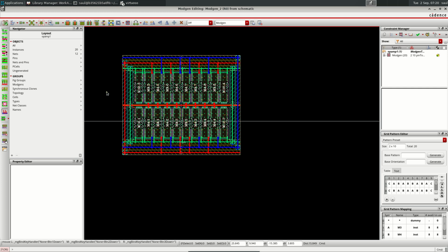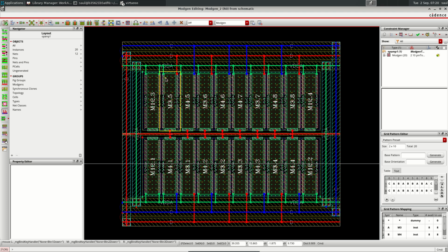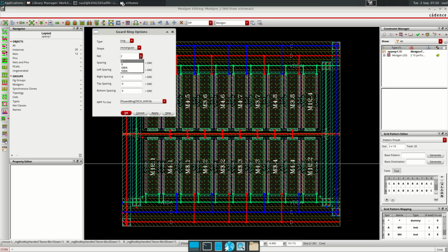Okay, as I mentioned before, I can continue connecting both sides if we want to greatly improve the connection and lower resistance, but maybe this will be more than enough. Later we check in the parasitic extraction if I need to do improvement in the layout. So one thing that I can do now is to add a connection and ring. Probably I will defer it to the layout part later, but we can just try here also to see that it is also possible to do it here.